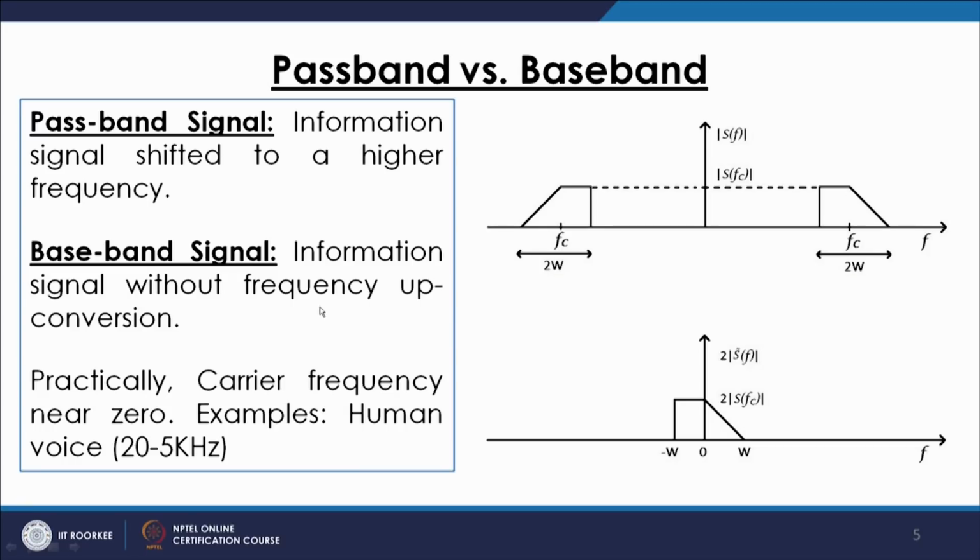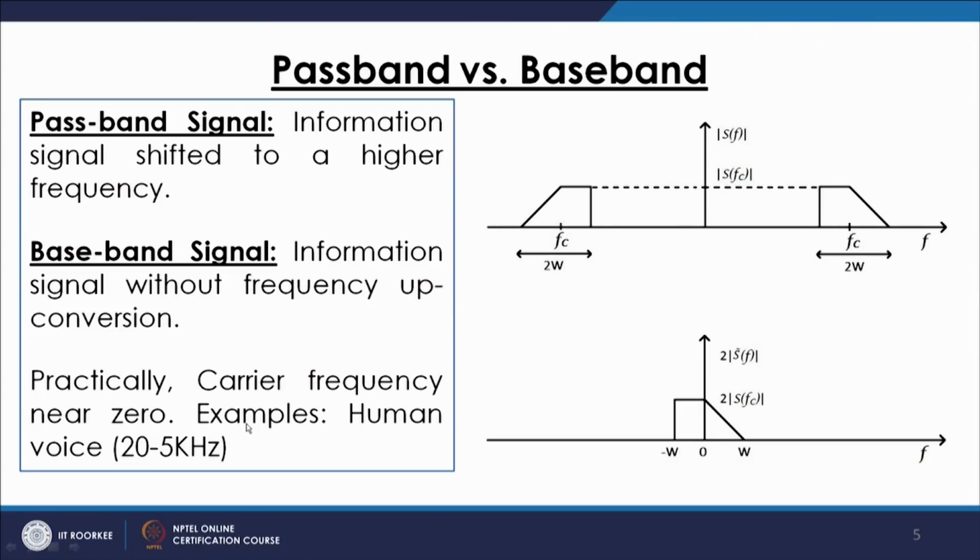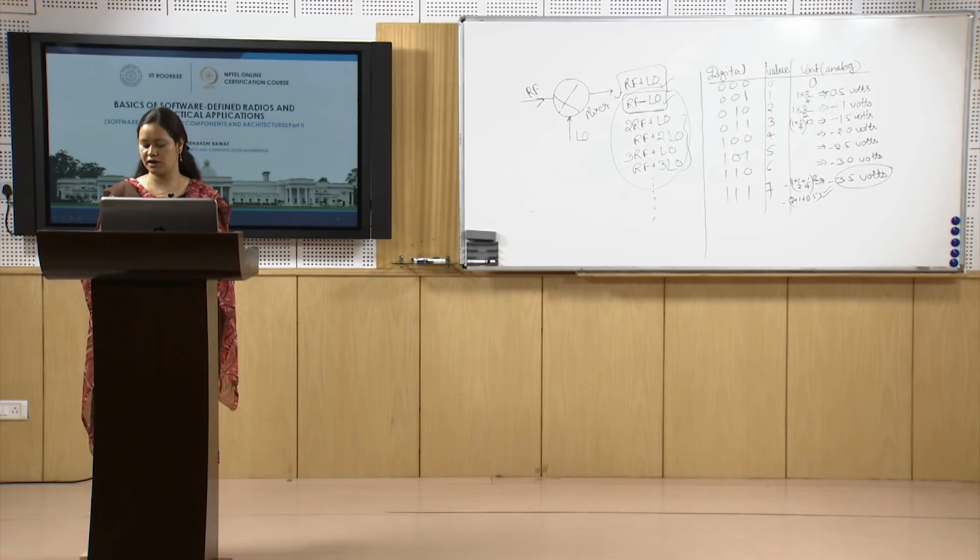A baseband signal is basically the frequency in the analog domain, where the information signal is near zero frequency. So whenever in the literature we hear about the baseband signal, it is a signal which is very near to baseband. Ideally it should be zero frequency, but practically frequencies near zero are also considered baseband signal. These are the frequencies which can be handled in the digital domain by using a numerical oscillator, etc. Now these components we will be covering later in this course.